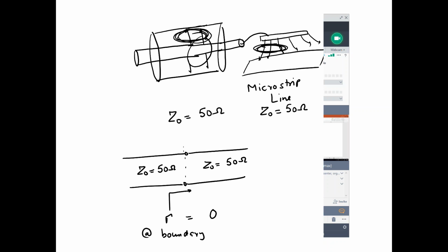In fact, when you go to high speeds and you have to send from one waveguide, from one kind of cable to another cable, you have to design some specific tapers which allow you to match the electromagnetic field from one to the other and achieve minimum reflections. So that transmission line model doesn't tell you the whole physics of what is going to happen.